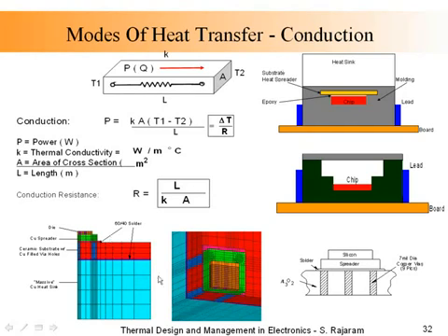And here's a finite element model of that. And here's actually the finite element model of a particular device that I showed you earlier. So we do finite element modeling at this level because it's all pure conduction. But at the surface, we have convection. So here is another package. Here is a chip sitting on a copper board.